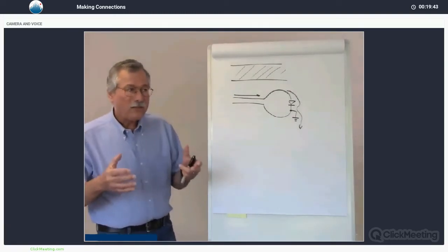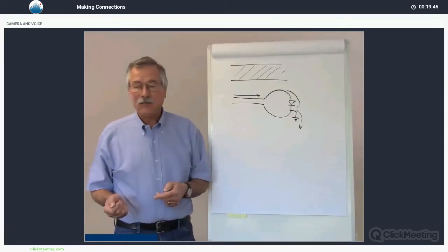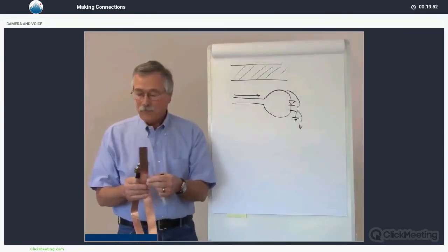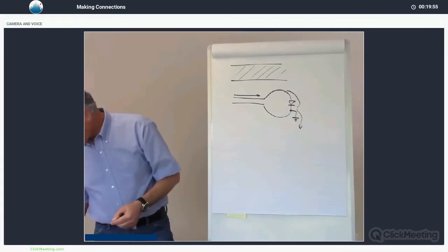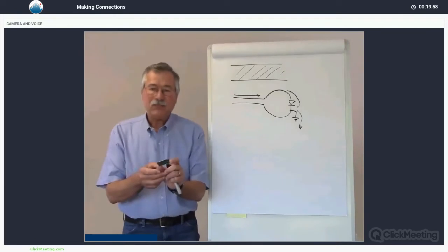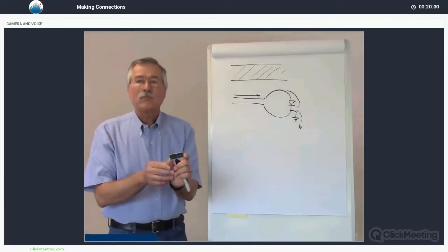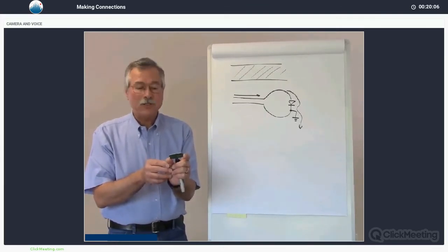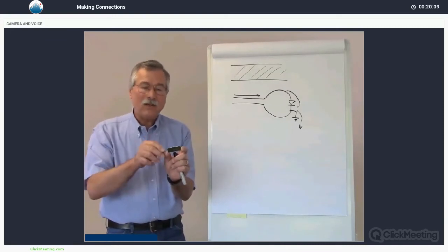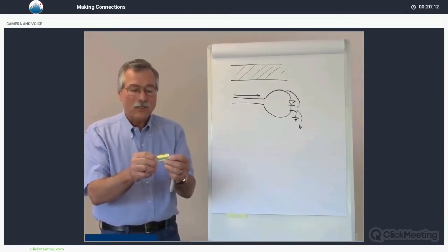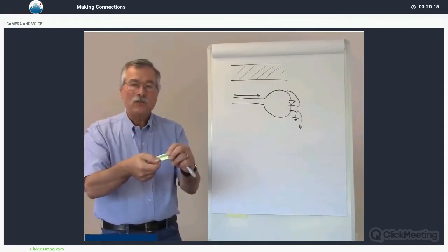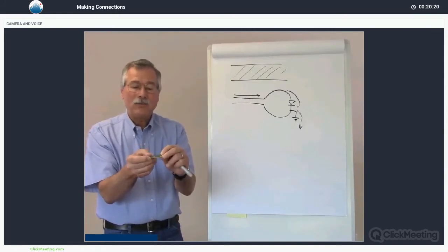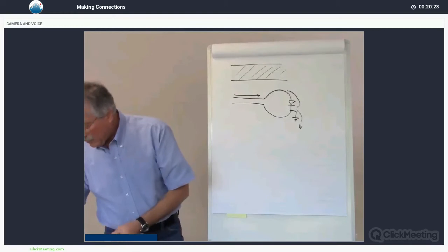The question often comes up, how do I tie strip line to my laser diode? The laser diode may not look anything like this. It may be in a very unusual package. Well, the best scheme that we've come up with is to recommend making a PC board. PC boards are cheaply made, readily available. You can hack one up by simply taking a two-sided piece of PC board material and a coping saw and cutting it out to match whatever sort of diode you have. You can then solder the strip line to the two sides of the board, nice wide flood solder connection, low inductance, and do anything you want on the other side of the board.